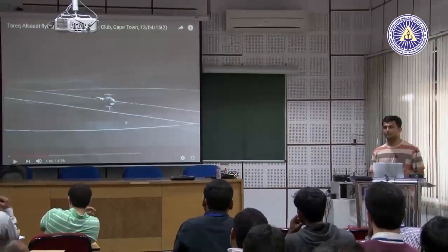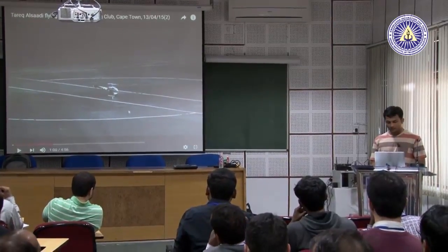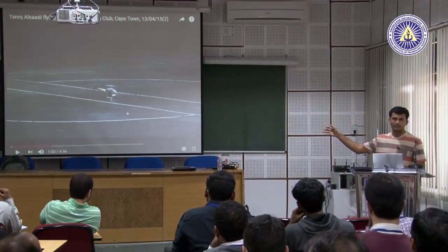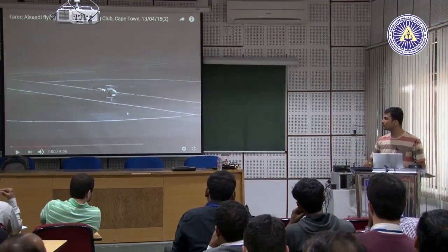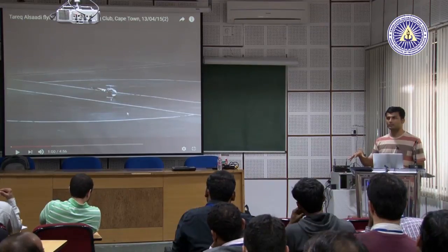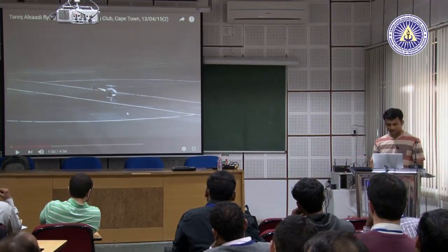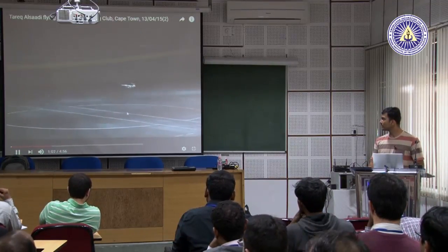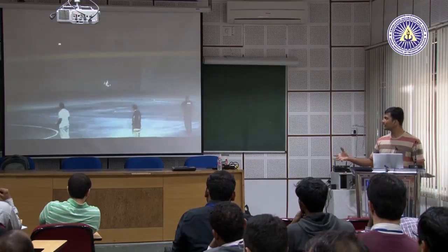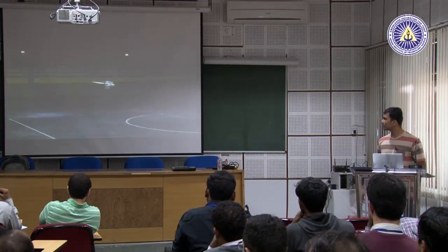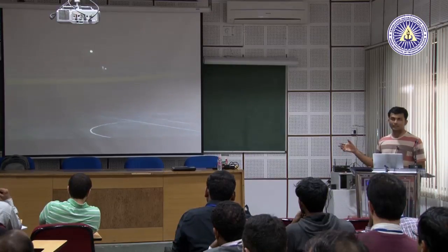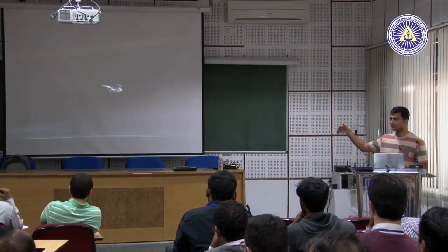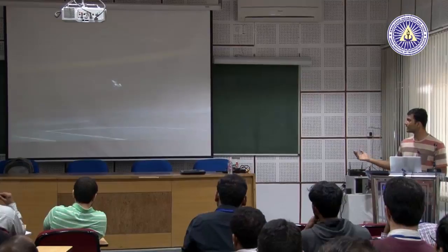Helicopter performing aerobatic maneuvers. This is manually flown, and we have the same size, same class of helicopter in our lab also. Its rotor diameter is about 1.5 meters, and it is capable of doing extreme aerobatic maneuvers. Let's take a look at this video. You can see that it's capable of attaining all altitudes, and also of performing high angular rate turns. It can also do inverted flight because the thrust can be inverted. It can generate negative thrust also.